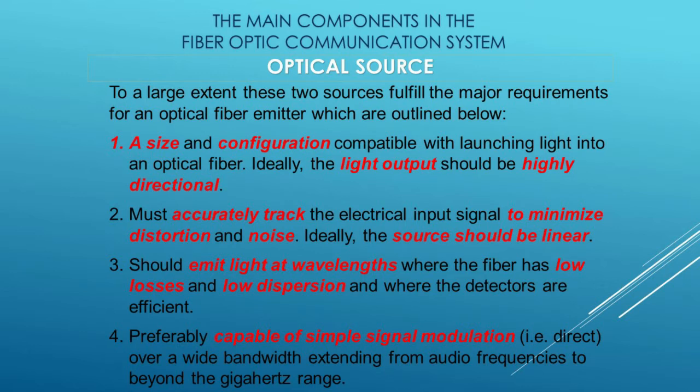1. A size and configuration compatible with launching light into an optical fiber. Ideally, the light output should be highly directional. 2. Must accurately track the electrical input signal to minimize distortion and noise. Ideally, the source should be linear. 3. Should emit light at wavelengths where the fiber has low losses and low dispersion and where the detectors are